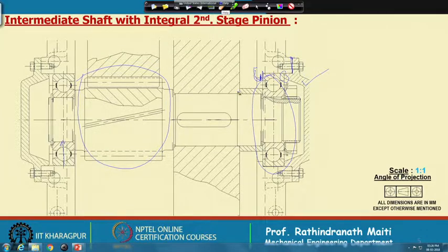First of all, a spacer is required to connect the gear with the inner race of the bearing, okay. And then it can be locked on the shaft by a circlip, simple circlip, but here we have used a lock nut and washer just to show.